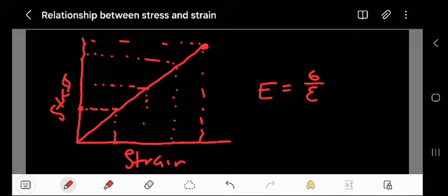Then they found there is something called the limit of proportionality. If you exceed that limit, your object will start to deform. Deformation is when it won't return to its normal form. Then there is the yield point. As you cross it, you come across things like the ultimate tensile strength, when you've reached the maximum stress which the material can resist.